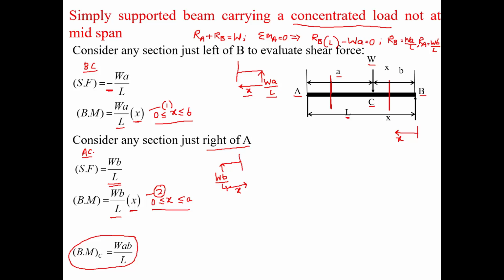The next task is to draw the shear force and bending moment diagrams. Please make sure that we get these equations for shear force and bending moment very accurately. Once we have obtained the shear force and bending moment expressions for both sections, we can draw the diagrams.